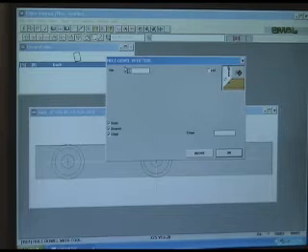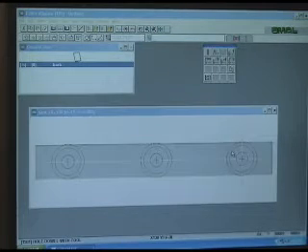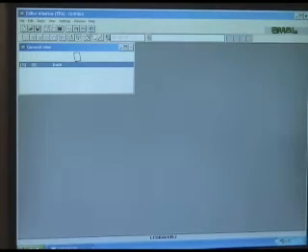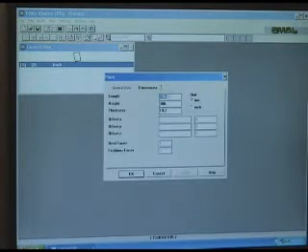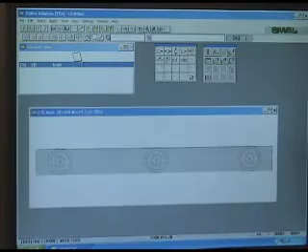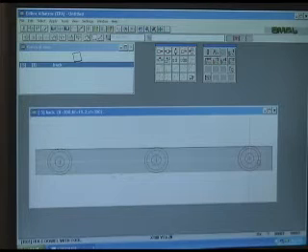I changed the line of code, so now I'm going to add a new line of code. And now we have a panel with 3 drill and dowel holes. This is parametric. If I close this and change the dimensions from 150 to 200, then in the new panel, the holes are consistent to the edge that they were referenced.